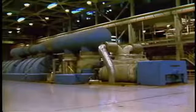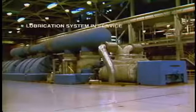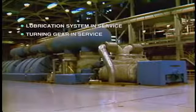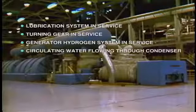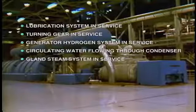Summarizing, then, the following conditions must be established before steam can be admitted to the turbine. Lubrication system in service. Turning gear in service. Generator hydrogen system in service where applicable. Circulating water flowing through the condenser. Gland steam system in service, providing sealing steam.